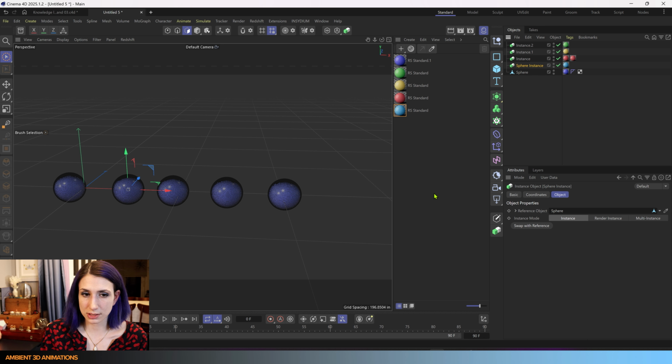So these settings are used in a lot of different places. So when you learn this, you've learned the settings for actually a lot of tools. The instance mode recognizes animation. So you could offset the animation of several objects, but you'll only be able to see it if you change the instance mode of those objects to instance.